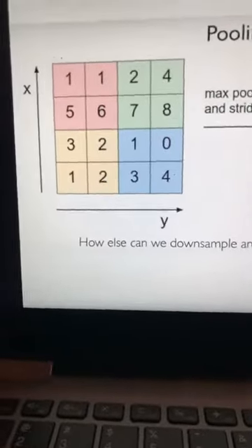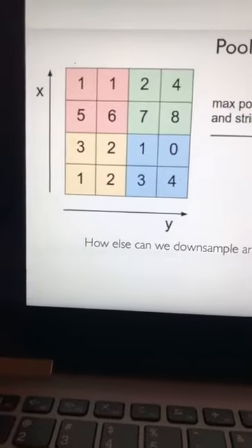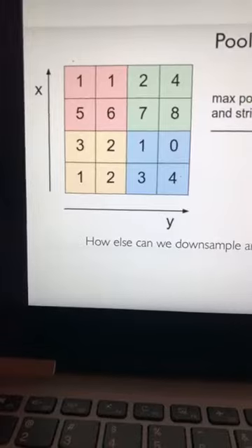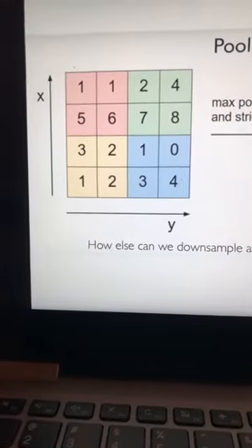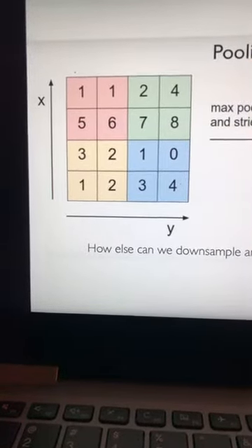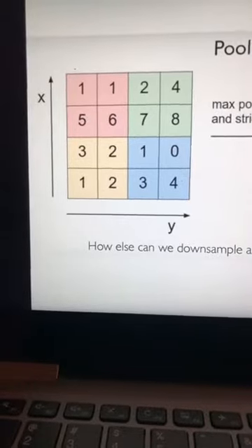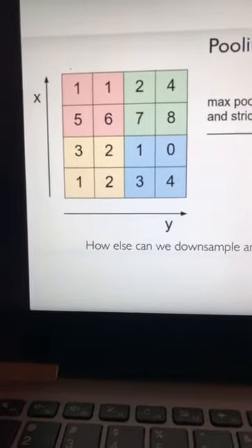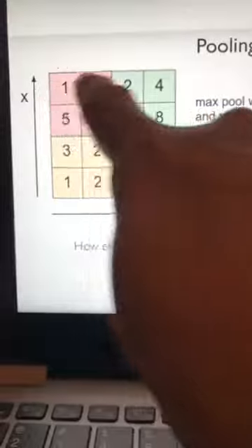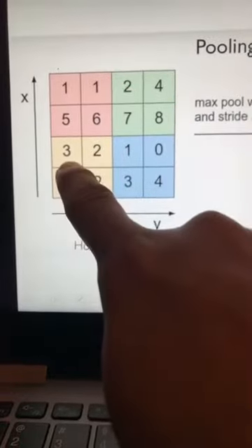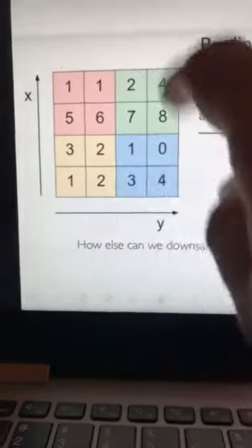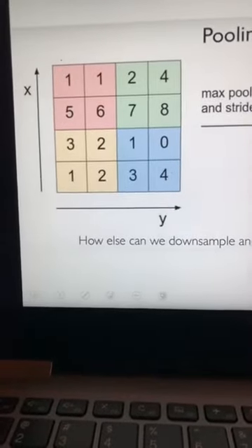So this is the process of decimation. Decimation means that you are reducing the size of an image. So every 2 by 2 block will be converted into 1 pixel. There are a number of ways of doing that. One is you systematically throw away samples. Keep this sample, then you keep this sample, then this sample, then this sample. So this 4 by 4 will be reduced into 2 by 2.